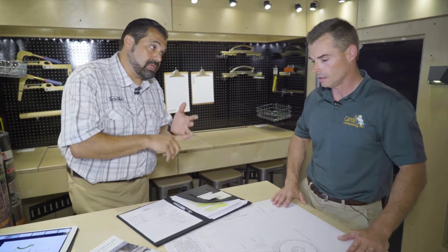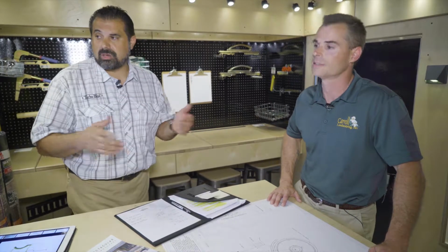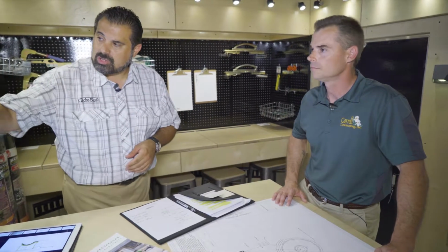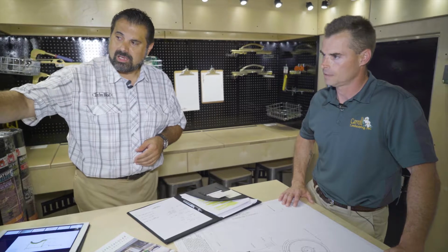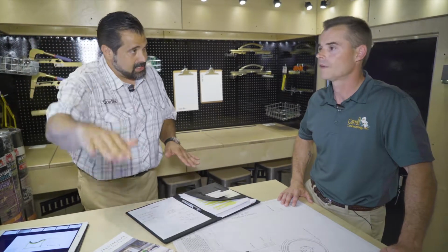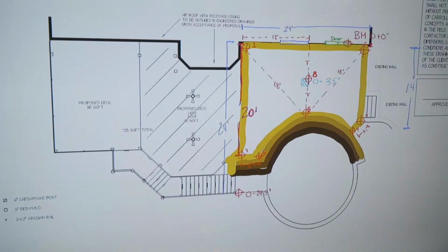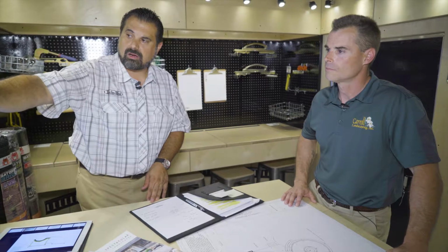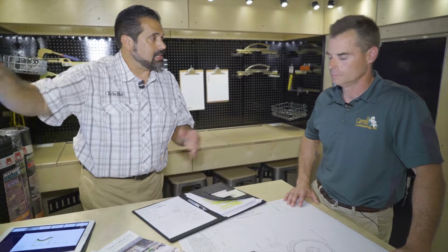We have a freeze-thaw susceptible climate, a frost line, we have snow in this environment, and we're also going to level across that wall because you don't want to go up and down those steps with a 1-inch pitch, stepping down here 6 inches, stepping down there 7. So all this is going to be level, and I see that we've got a drain drawn in here, all pitched over to that drain, and then eventually out to the environment, which is cool.